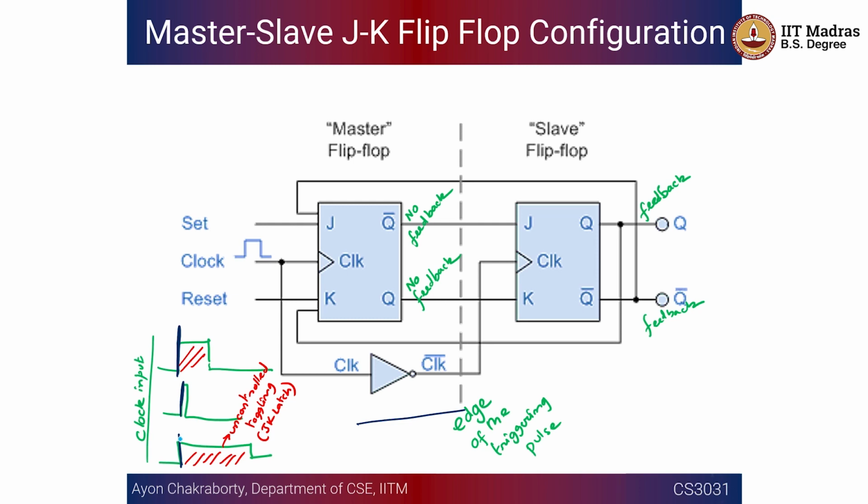Okay, and no longer toggle will be done because it doesn't matter how long it is on, whether for a narrow amount of time or a wider amount of time. Next time when you get another trigger, the value will be toggled again. This is very important because now you can control the toggling in a more deterministic way. This could be used for implementing a lot of different circuits or state machines that use JK flip-flops.